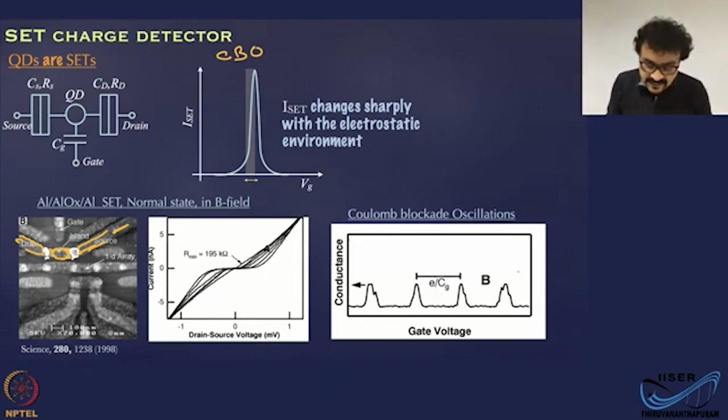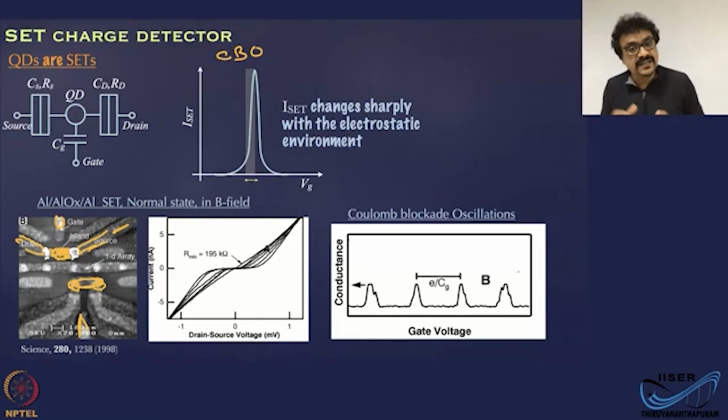You can see another single electron transistor here, with two tunnel junctions and an island, and a gate here for that. There is a gate here which is coupled to this island. And in the current voltage characteristics, we will observe a blockade which you can lift by applying a gate voltage.